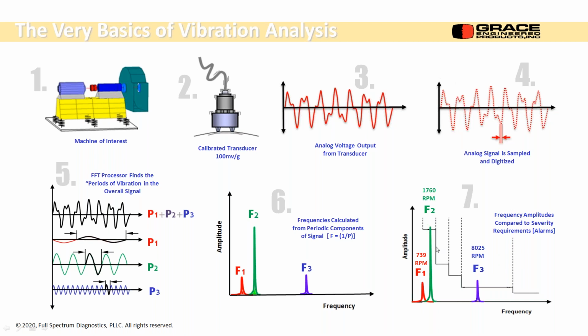If I know where 1 times RPM is, I can make my stair-step pattern. And this we talked about a little bit, I think, last Thursday. This stair-step pattern is giving me alarms on each frequency band. Okay, so I have a whole series of alarms now. And we'll get a little more into that. So we're answering the question, how much is too much? So if any one of these bands produces an amplitude that's above our limit, like this one or this one, we can go in and do some analysis and figure out what's causing that, and how we can deal with it.